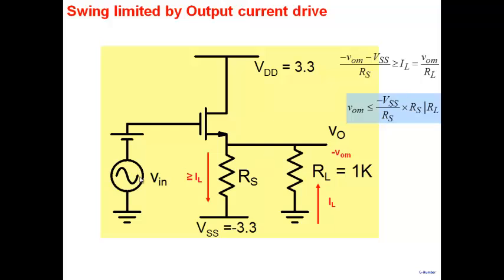Okay. In all of this, we are assuming that the DC value of output voltage is 0. The reason being that I don't want any DC current flowing into my load here. I've not used a coupling capacitor here, because we would be interested in using this amplifier on an IC, let's say, and therefore we've avoided any coupling capacitors here. And therefore, the output DC value is 0, and the net voltage then at this particular node, we are calling it minus V0M.